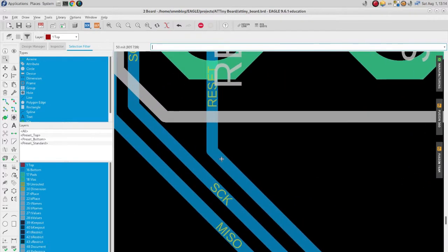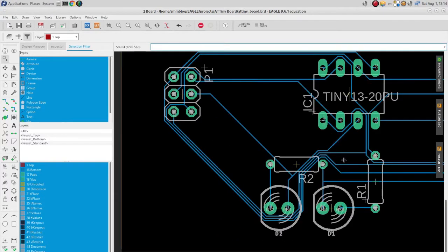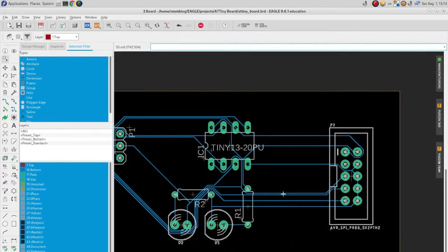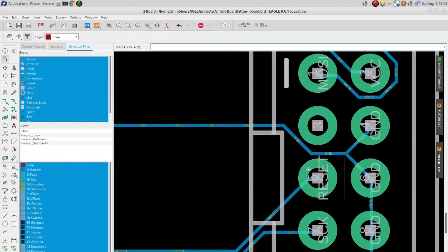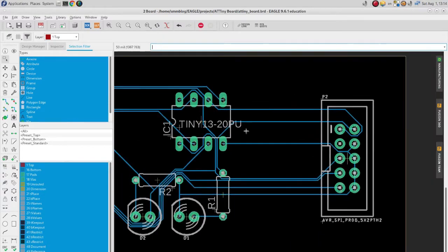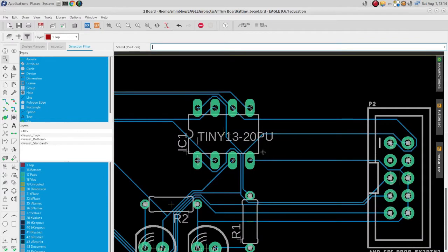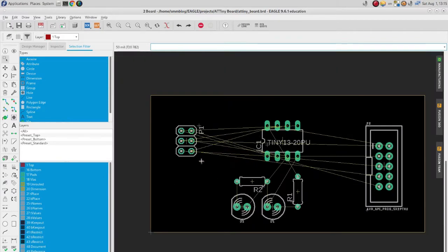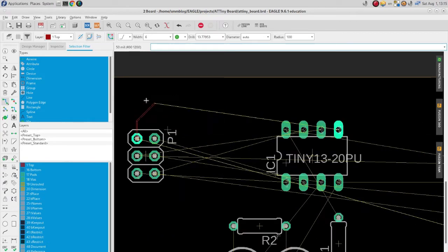And here comes the first design limitation of your PCB due to manufacturing, which is the trace width and the clearance. Your copper trace width should lie between 0.4 mm at minimum and maybe 2 mm on average. The clearance, which is the shortest distance between two adjacent copper traces, should also lie between maybe 0.5 mm and 1 mm on average.